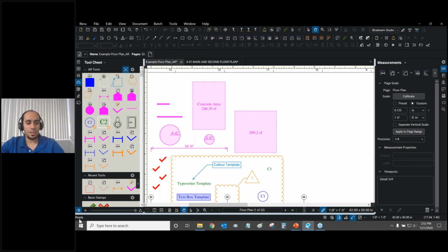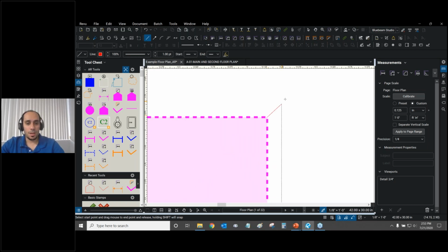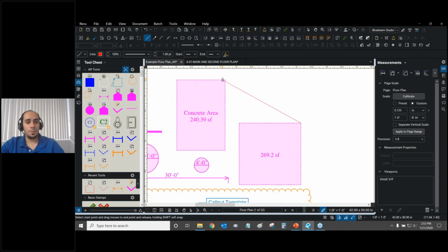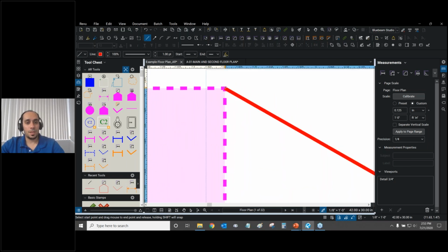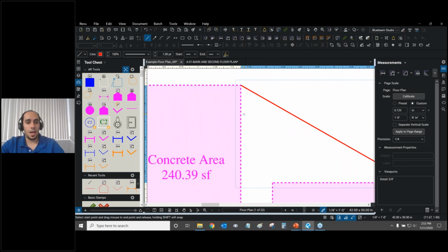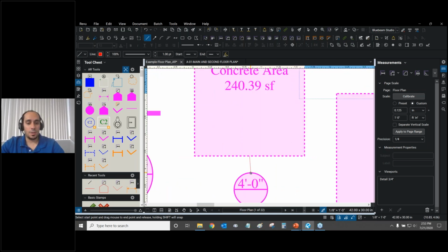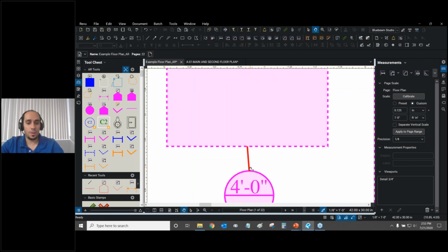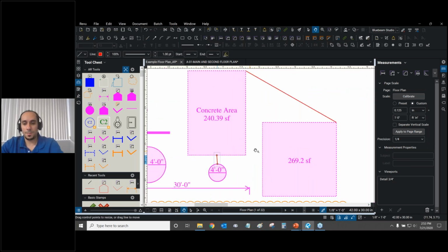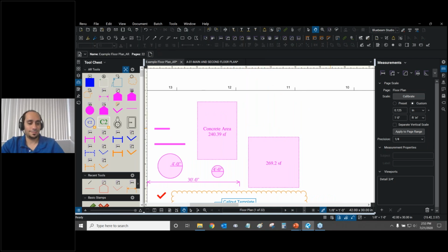That status bar is found down here. So we have all of these options right down here. And the one that you're looking for is snap to markup. So when I turn that on, now I can take any tool. I'm just going to take the line tool, for example, and I can snap to the exact corner of this markup, and I can go from markup to markup or anywhere else I want. So there we go. And you can see that I'm using these grips. I have basically nearest grips, endpoint grips, midpoint is right here, and there we go. I can now snap perfectly to the midpoints of these markups right here. So yep, good question. All right, thank you.